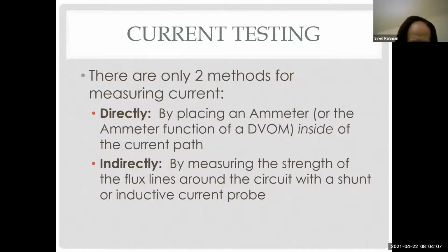I can actually use current to tell if all of my cylinders have the same compression or not on the engine. So here I'm going to test the starter, but show you at the same time, I can do what's called a relative compression test, which tells me if all the cylinders are the same, which is obviously much quicker than the old mechanical way of getting a compression gauge out and testing all the cylinders individually.